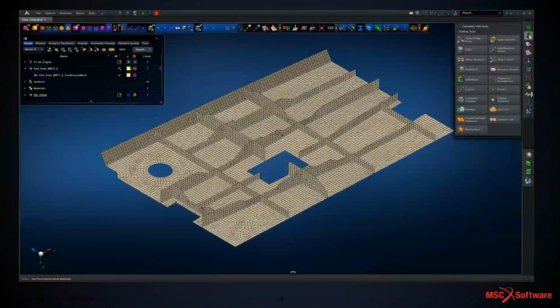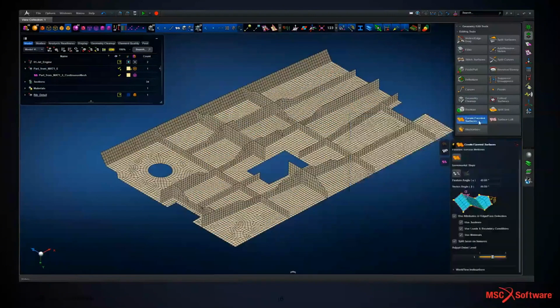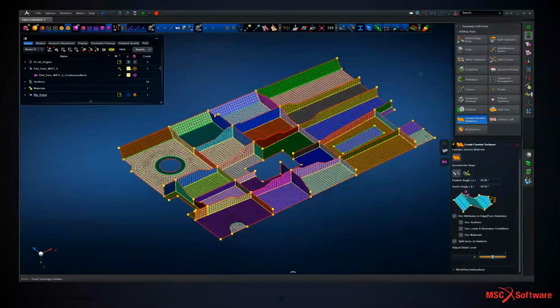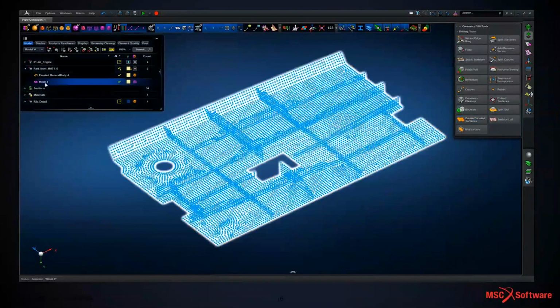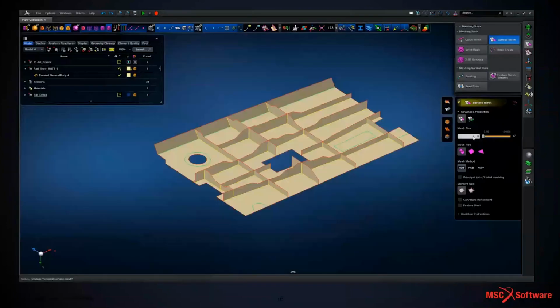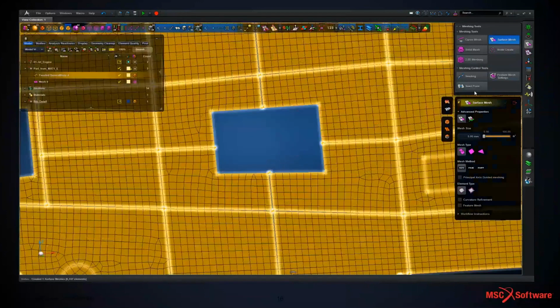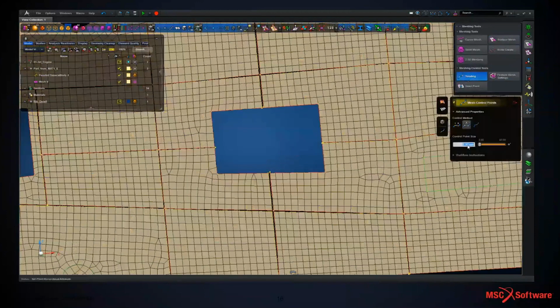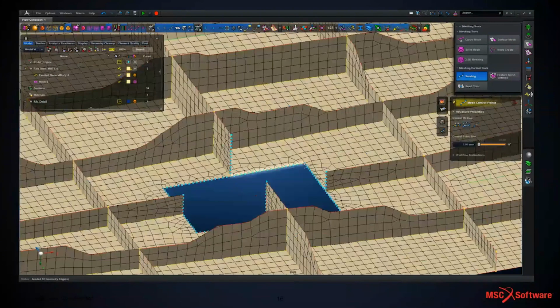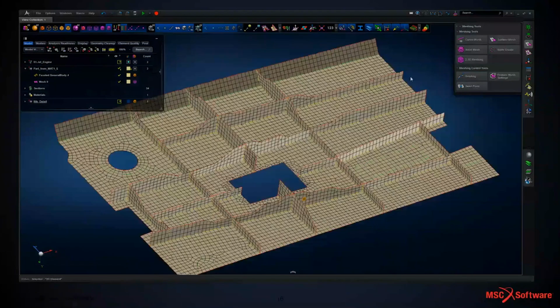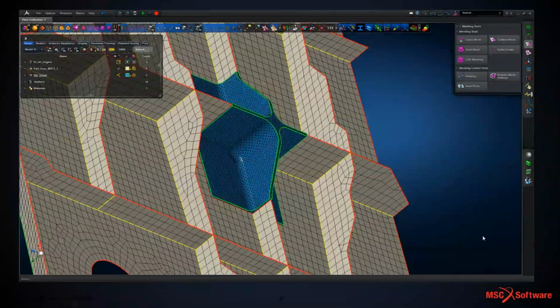And from that mesh, we're now going to use the geometry tool, create faceted surfaces. So pick the single mesh, and Apex will evaluate those surfaces and generate a single set of geometry objects, which we can now delete the mesh from the browser tree, and then remesh that surface using a different element edge length, and we've got the full control of geometry edit tools, so we can now seed an edge, for example, so we can just remesh. And the key thing here is that the faceted surface has remembered the shell element thickness, so we don't need to then repopulate based on the new shells that we've created.